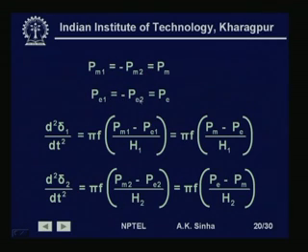So, PE1 minus PE2 is equal to PE, and now substituting this expression in the swing equation, we will have d2 delta1 by dt2 is equal to pi f by H1 into Pm1 minus PE1. So, we can write now this Pm1 minus PE1 as Pm minus PE from here. Pm1 is Pm and PE1 is PE. So, we are writing pi f Pm minus PE by H1.